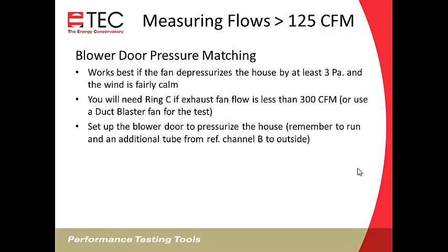You'll set up the blower door frame and the fan, and you'll pressurize the house. So remember, when you're pressurizing, you have to turn the fan around, and because we're using it to measure flow, you can't use the reverse switch on the blower door fan. You need to turn it around, so now the rings are on the outside. So there's a few steps in there. You have to take a baseline reading, and now your rings are on the outside.